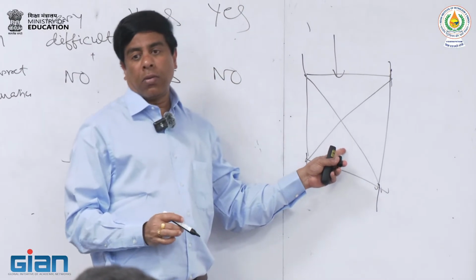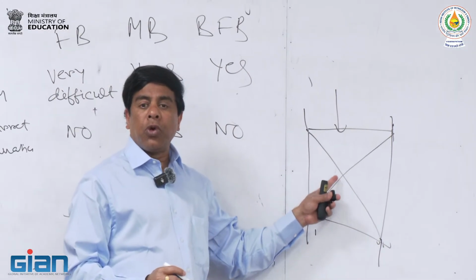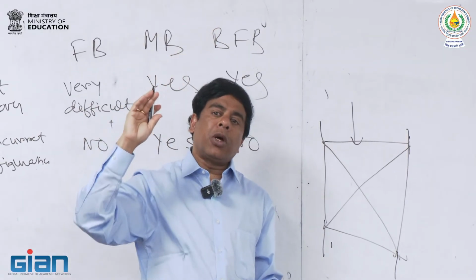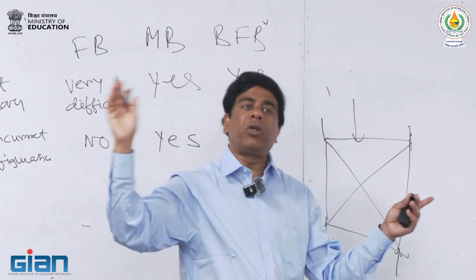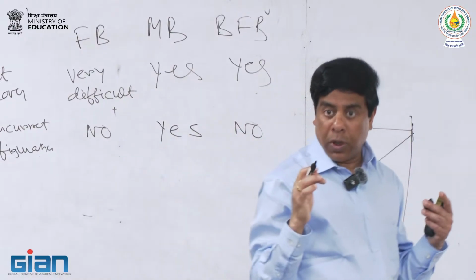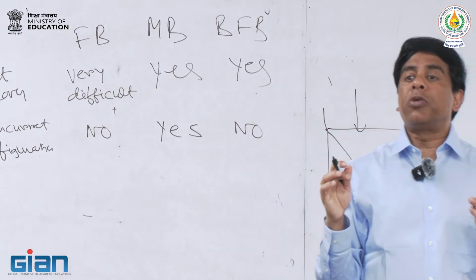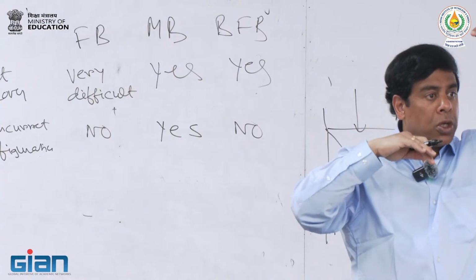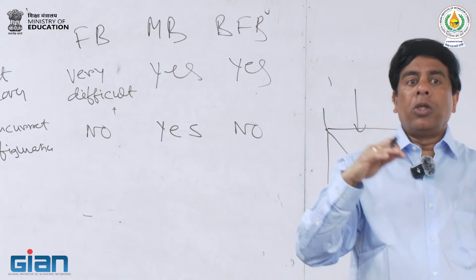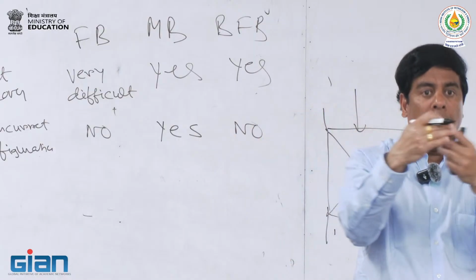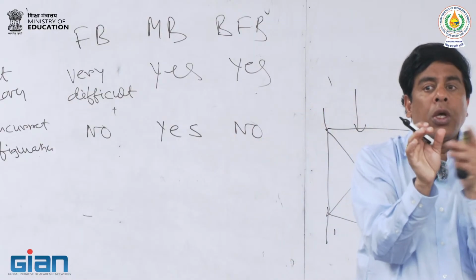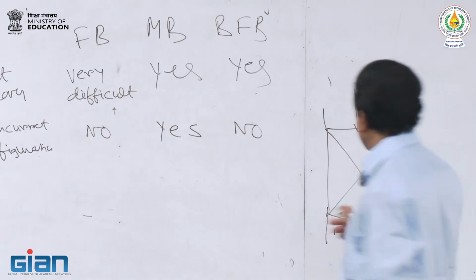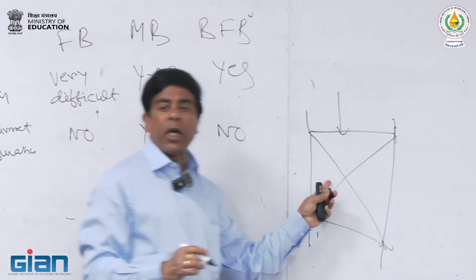Remember, in a fixed bed system, what we are basically saying is that if I have something like that and the gas enters here, this solid is static. If I could move the solid in the opposite direction, that would give me the counter current configuration. From all our chemical engineering principles, counter current gives us the best driving force. That's why absorption and distillation towers are all counter current.